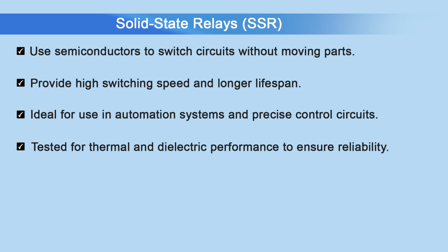Next, we will see the solid state relays, SSR. These solid state relays use semiconductor components to perform switching operations without any moving parts. They offer faster switching times, longer lifespans and are more resistant to shock and vibration compared to EMRs. The solid state relays are commonly used in applications requiring high speed switching such as industrial automation, heating control and motor drives. The testing of these relays focuses on verifying the integrity of the semiconductor components. Dielectric and thermal testing are crucial in this case to ensure the relay can handle the required voltage and current levels without overheating.